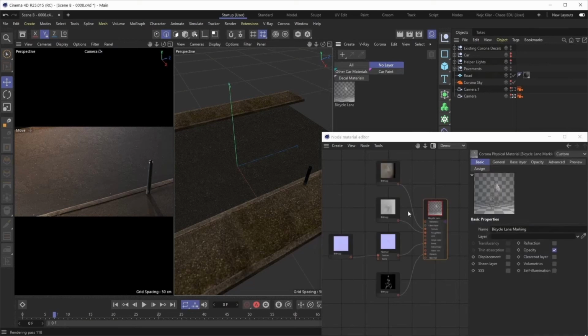It's the same exact material that we've created in 3ds Max. We just pre-prepared it just to save some time. As you'll see here, you have that same albedo map, that same roughness map, same normal map, and that same opacity map as well. So what we're still missing is a Corona decal in our scene.